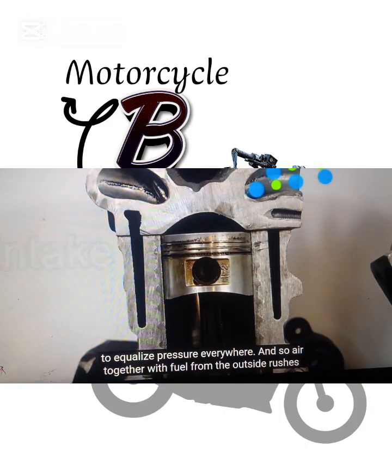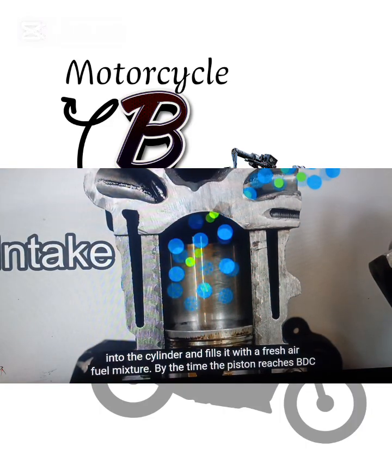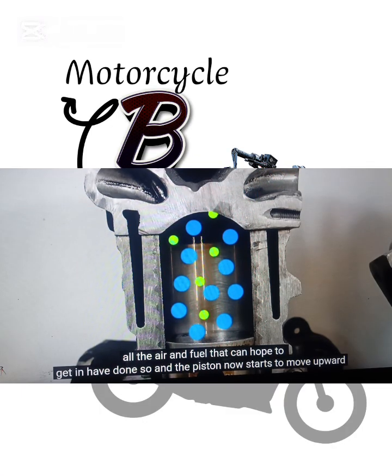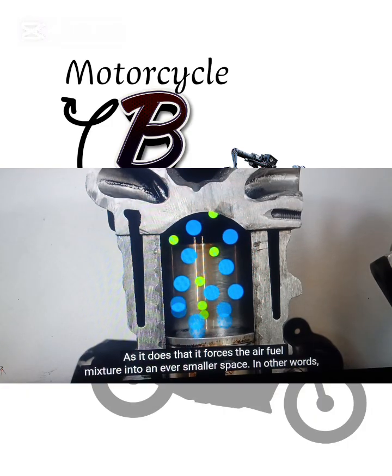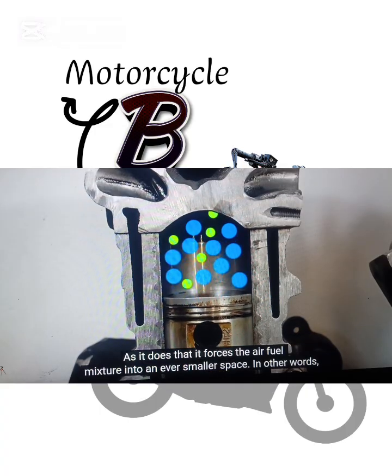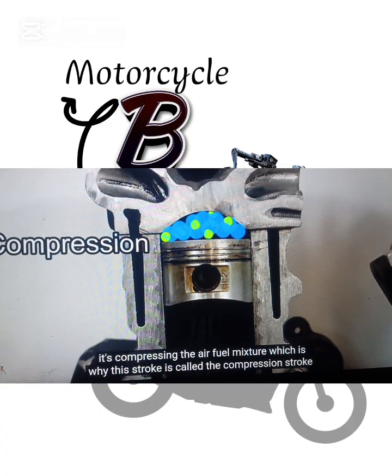And so air, together with fuel from the outside, rushes into the cylinder and fills it with a fresh air-fuel mixture. By the time the piston reaches bottom dead center, all the air and fuel that can hope to get in have done so, and the piston now starts to move upward. As it does that, it forces the air-fuel mixture into an ever smaller space. In other words, it's compressing the air-fuel mixture, which is why this stroke is called the compression stroke.